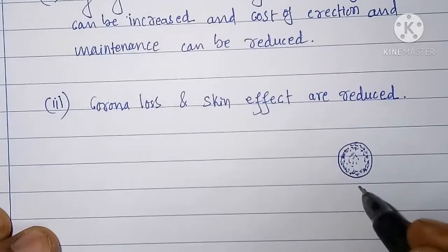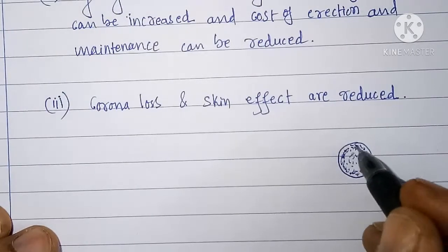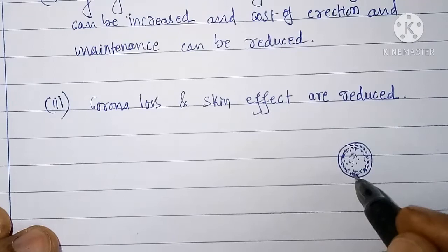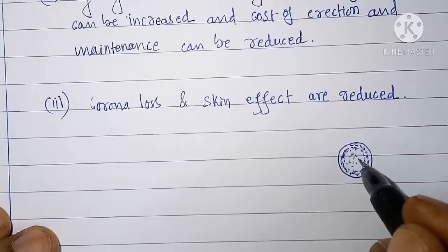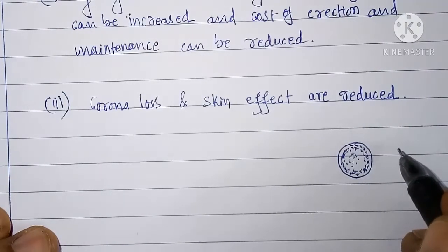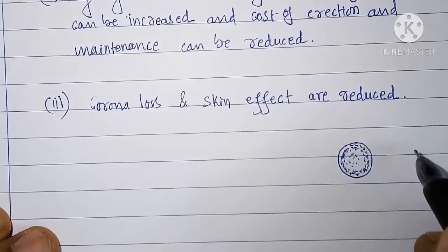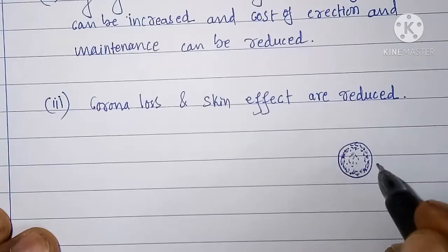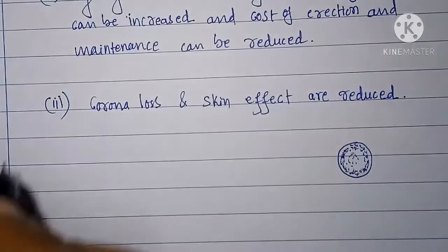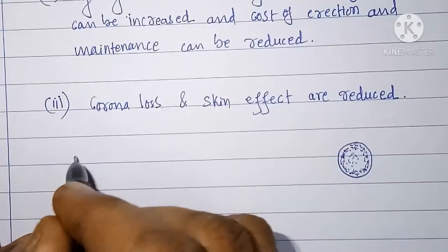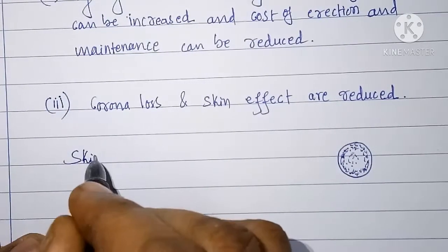And if the frequency of the current increases, then the current density near the surface will further increase, and at the center the current density will further decrease. This effect is called as skin effect. So you just note down the definition of skin effect.